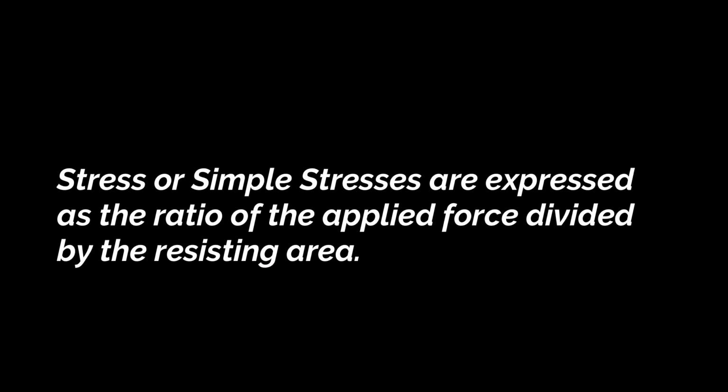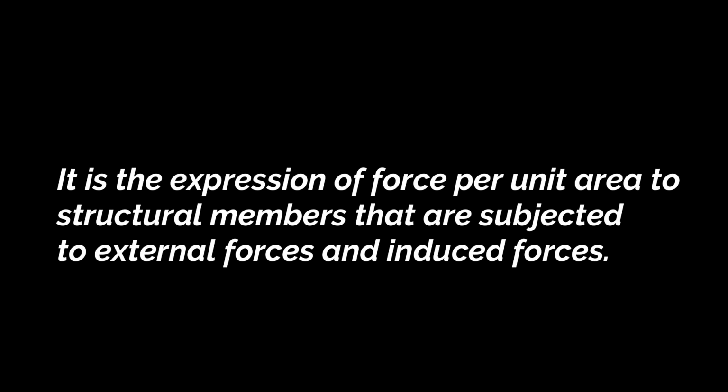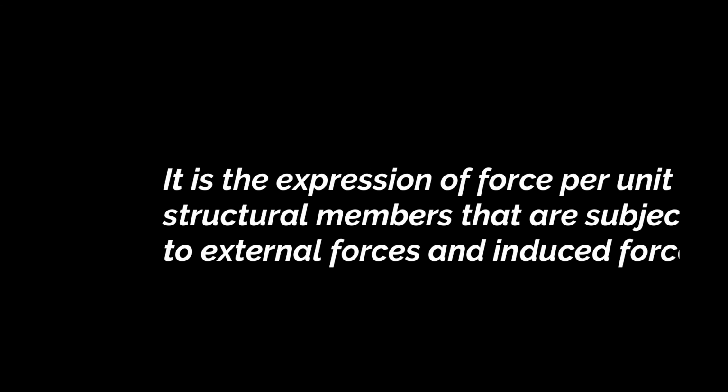Today, we are going to solve one of the problems of the mechanics of deformable bodies, specifically the topic about stress. But before that, we are going to define what is stress. Stress or simple stresses are expressed as the ratio of the applied force divided by the resisting area. It is the expression of force per unit area to structural members that are subjected to external forces and induced forces.